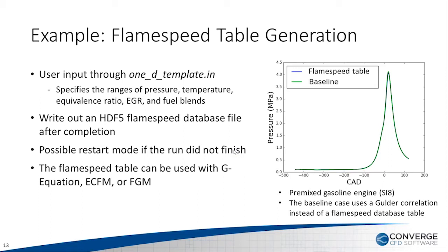Because by default we use the Newton solver to solve, sometimes if you run 1,000 points, there may be 1, 2, or 10 points that are not converged or do not have results. So it allows you to restart these separate points to finish your table.